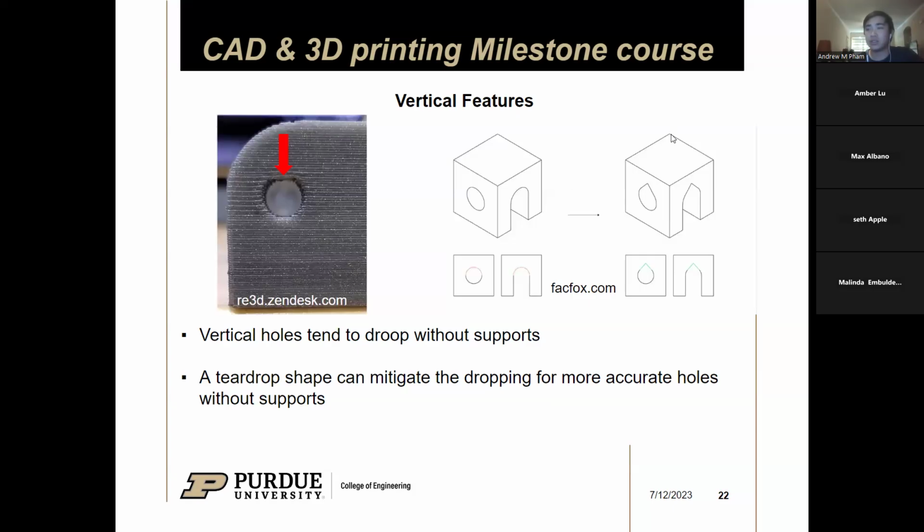So again, those are a couple of geometric constraints that I use to make this teardrop. Oh wait, the other one is to make sure that these lines are tangent to the circle to ensure a smooth transition. But those geometric constraints should be enough to create that teardrop shape for you. And again, because these two lines are perpendicular to each other, the overhang angle at the top of this teardrop is 45 degrees, right? And again, 45 degrees, it's a good number. The printer should be able to reproduce it, and life is good.